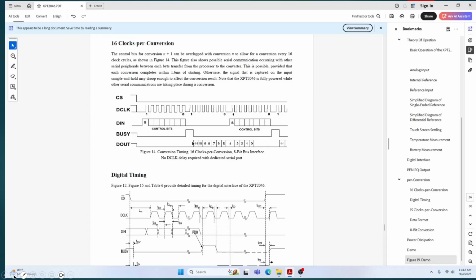So the way this works is the first word that you get, the 8 parameters, 1, 2, 3, 4, 5, 6, 7, and 8, are going to be the most significant bits of the value. Then you make another request, and you are going to get the other 4 less significant bits.